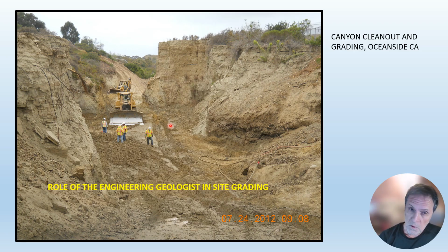So grading can involve a lot of things. It can involve the removal of expansive clays. It can involve landslide repair, improvement of slopes, whether they're cut slopes or fill slopes, something to improve the underlying masses of soil and rock, make them more amenable to construction, as I've already said. So it's land modification. You may end up building pads for homes or buildings, flat pads. You may put in slopes, cut slopes or fill slopes. You may put in roadways.